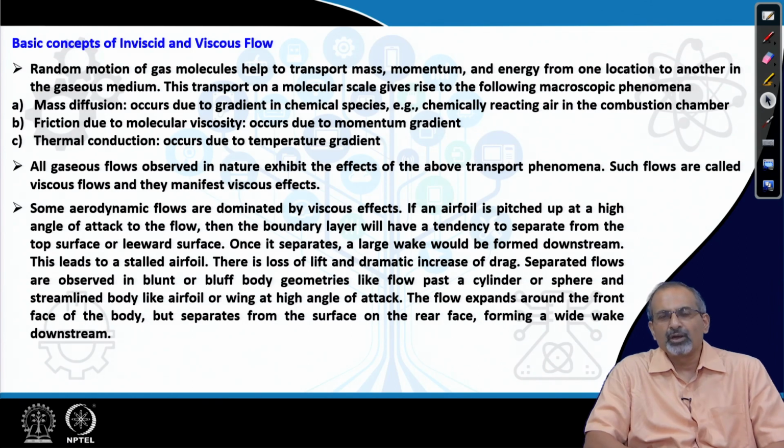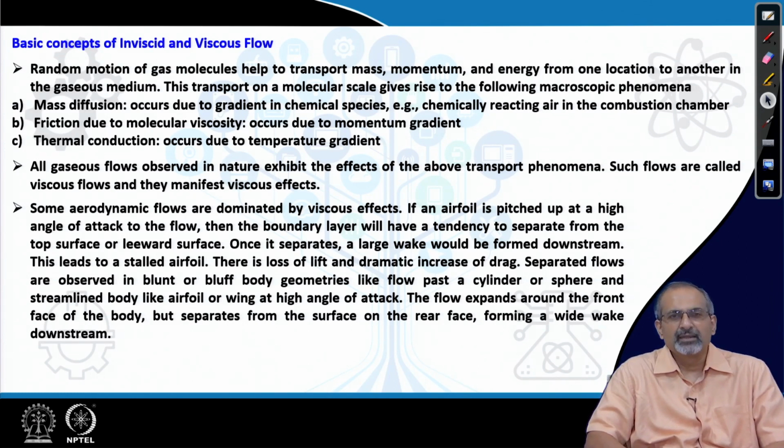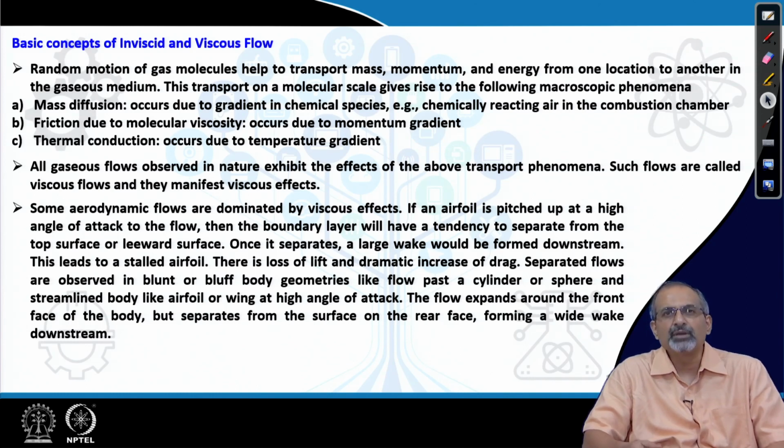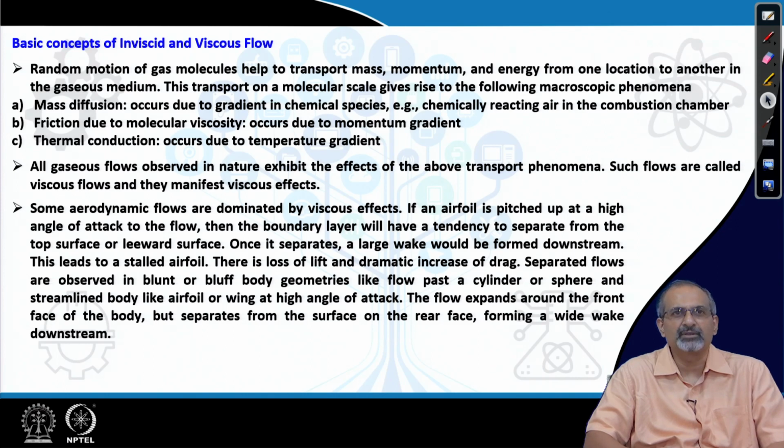So, if an airfoil is pitched up at a fairly large angle of attack, then the thin layer which is affected by viscous effects around the airfoil has a tendency to move away from the surface and separate from the surface of the airfoil, especially on the top surface, which we call the leeward surface.